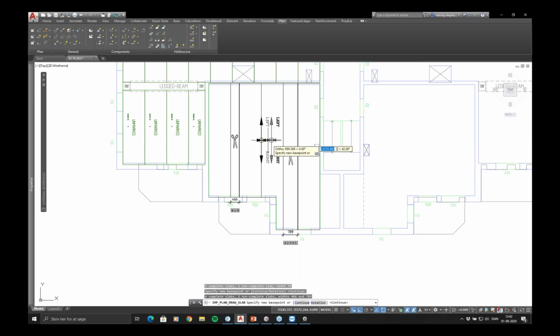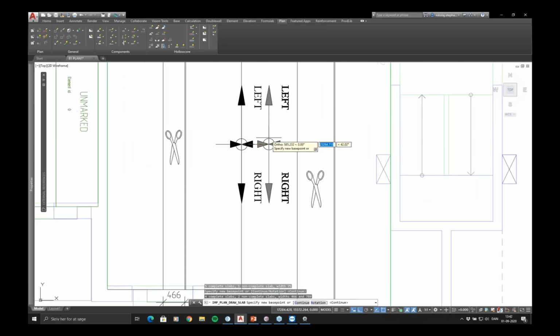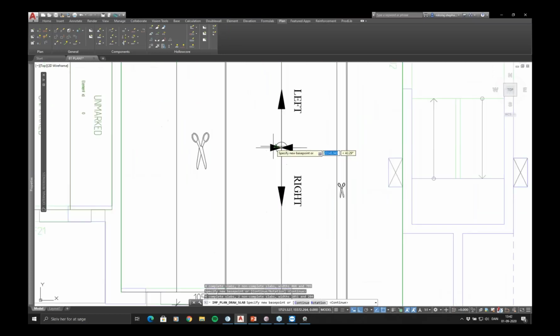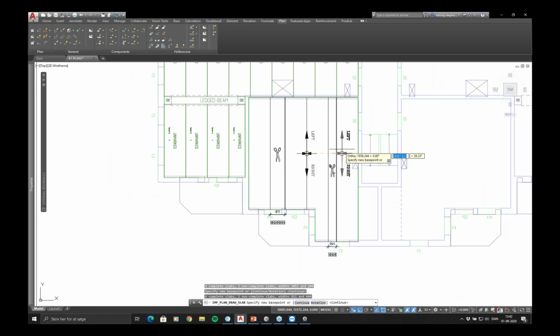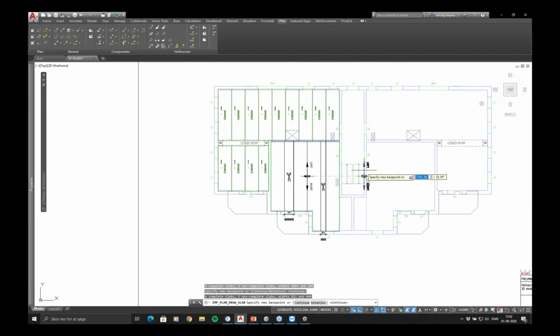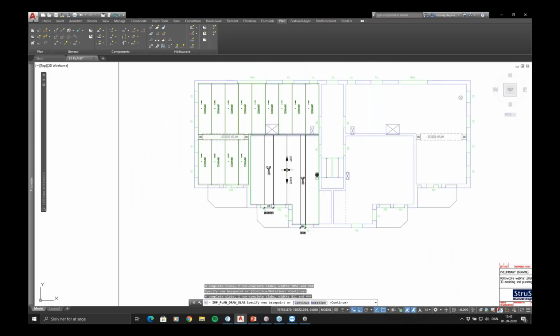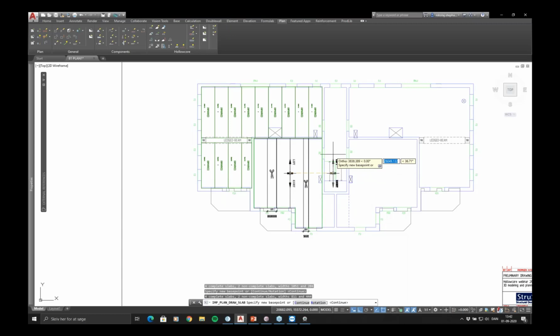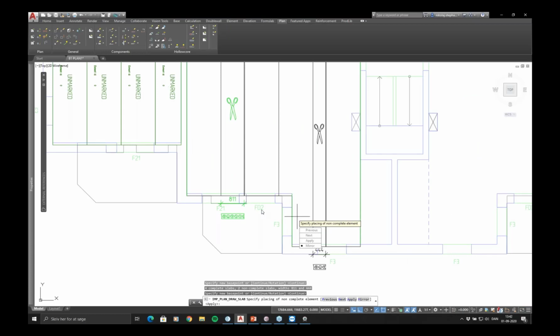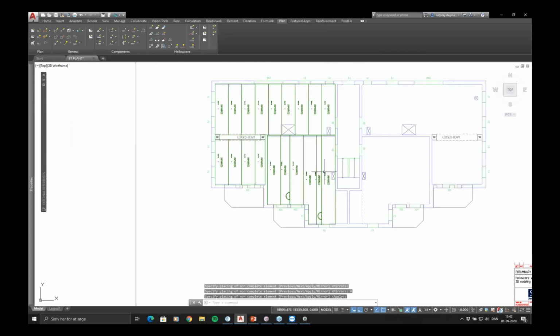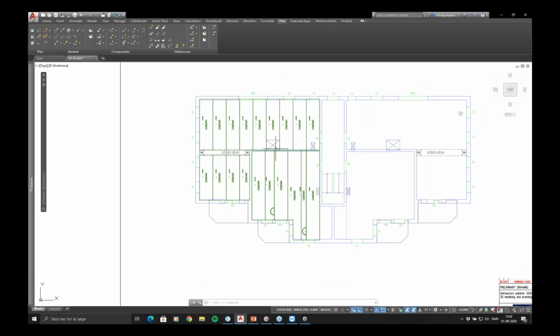But what I want to do is change the zone where I cut the hollow core to something that fits a little bit better. So getting a little bit more realistic hollow cores here. I might want to call up the client and tell him this is not possible, this is bad to have a small hollow core like this, and so on and so forth. But right now, let's just design ourselves out of it. So that's fine here. I can even mirror the cut of the hollow core if I want, or I can of course just apply it here. So now I have a layout of hollow cores here.